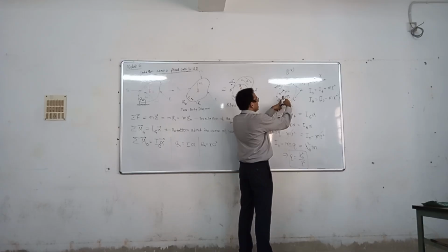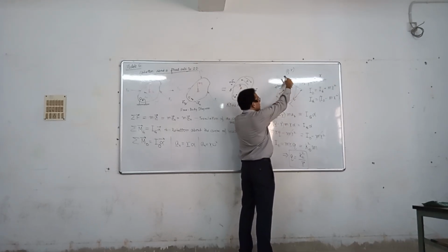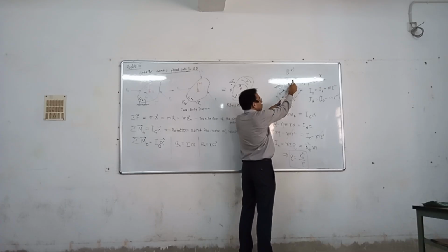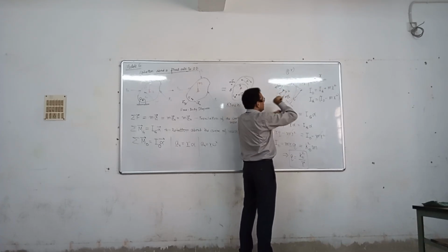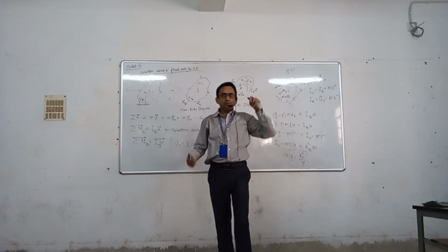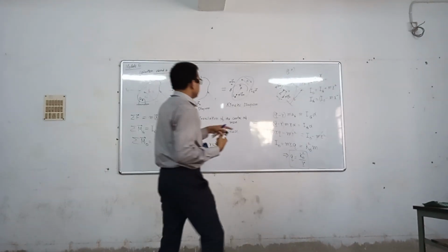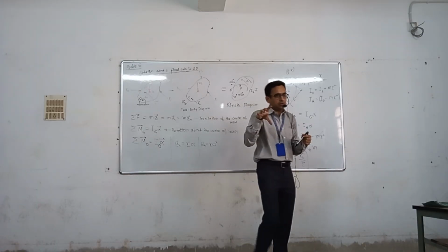You see that all the forces are passing through this point, because this is the component of tangential force and this is the component of normal force. Therefore, through this point all the resultant external forces are passing. So if forces act through this point, there will not be any tangential force acting on my hand or whatever the bearing is.